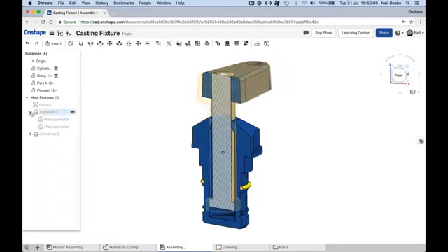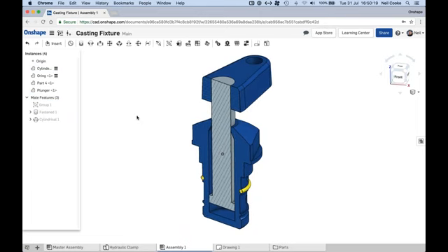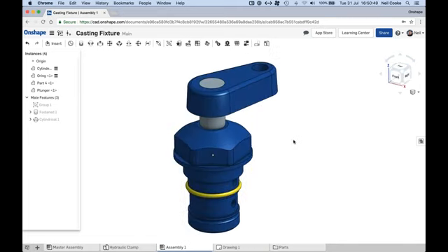Okay, so you can see here we've got a group and two mates. Whereas if you do that in SolidWorks at least, then you've probably got an insert and a mate, an insert and a mate, and at least four or five mates as opposed to the two that you would have in Onshape. So once things start to get more complex, and you get larger, more complex assemblies, then you'll see that your mate features list will be considerably smaller than you might be used to seeing in SolidWorks or indeed Creo.